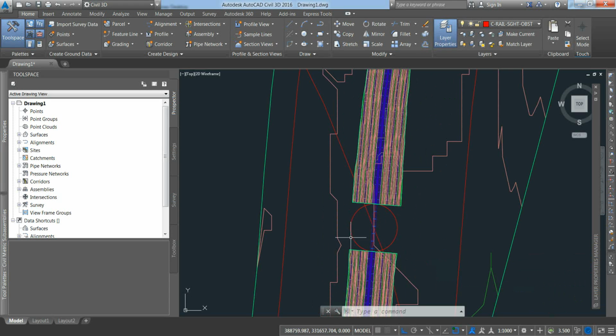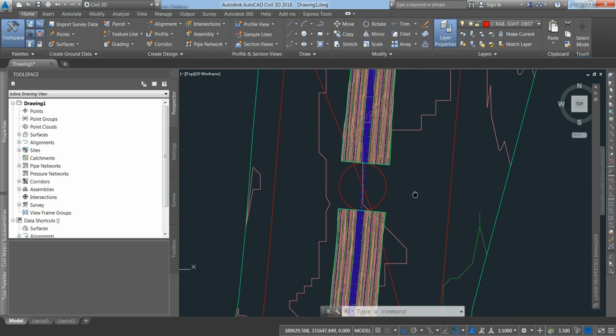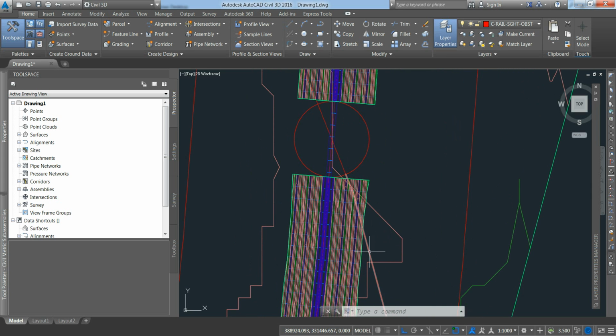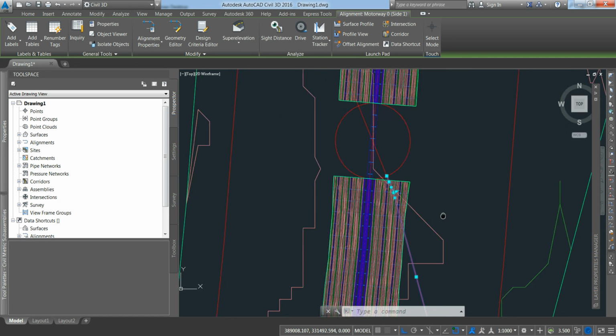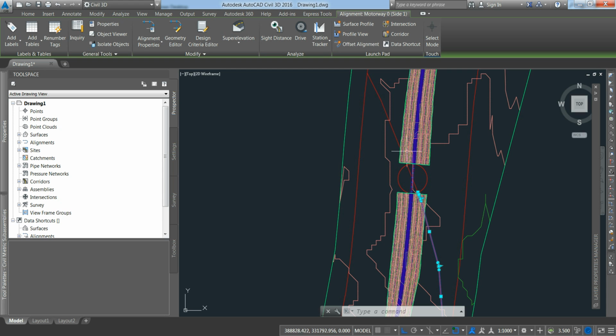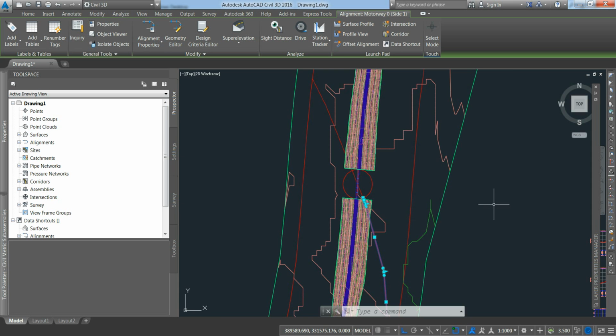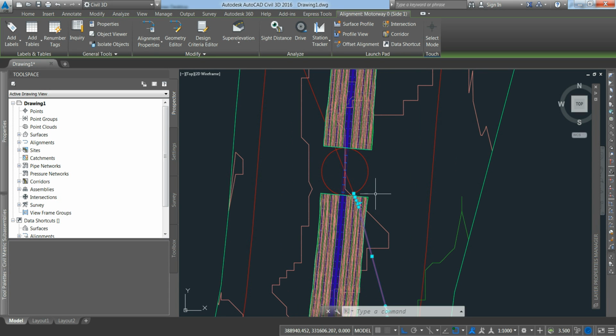So initially we've just taken an arbitrary radius, and that determines what the gap should be, which may not be correct. Looking specifically on this item, you can see that the centre line of our alignment, regardless of any further width that will be added when we build the corridor for this item, we know that at this point we're going to have to change whatever the design is, because the bridge that's going to be required would probably be over 300-400 meters long. So an alternative solution to get this asset crossing our railway will need to be produced.